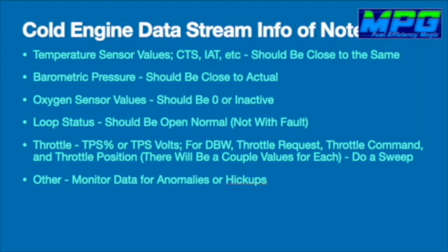Then we want to look at temperatures, air intake, coolant. If you have an HVAC sensor, cat temp, anything that's temperature related, we want to make sure that they're all pretty close to the same. They may be a degree or two off. It actually will increment, I think, by 2 degrees Celsius. So if it's off 2 or 4 degrees, that's no concern.